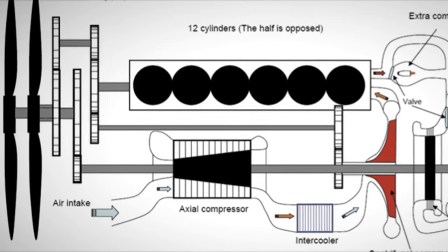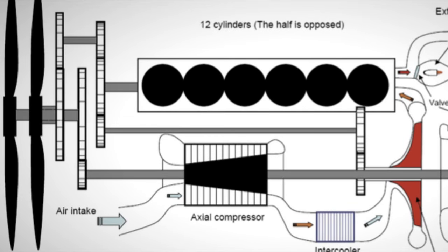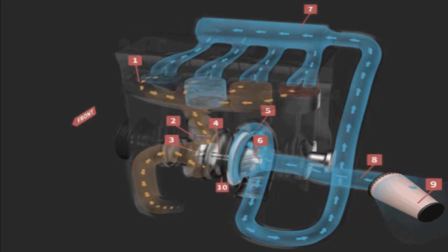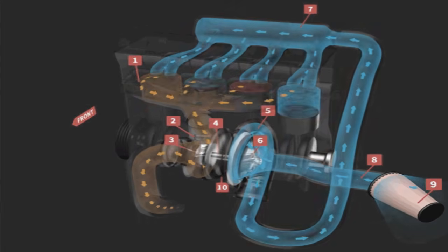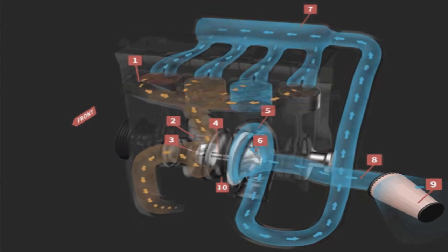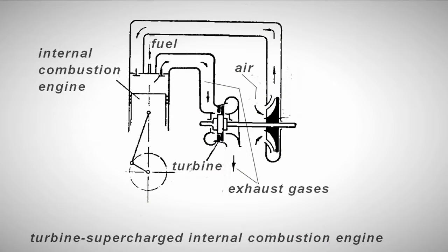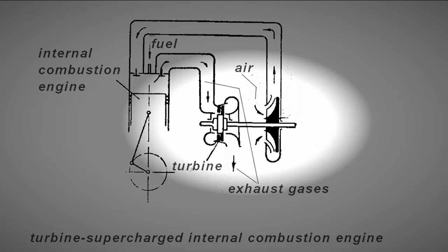However, these are very complex design options, requiring the use of complex transmissions. It would be simpler and more efficient if the turbine transferred its power to an air compressor, which would then force air into the engine cylinder. In other words, turbocharging the engine. The benefits of turbocharging are well known. Increased engine power, reduced engine weight relative to its power output, reduced fuel consumption, and more. The turbine's work in this case will be approximately equal to the compressor's, since they are located on the same shaft.